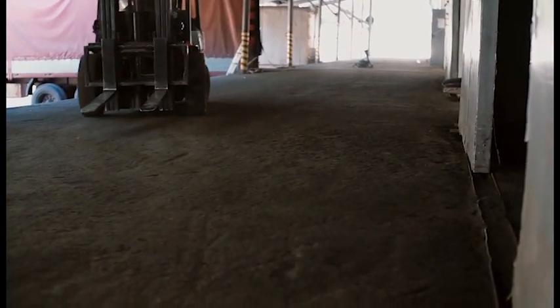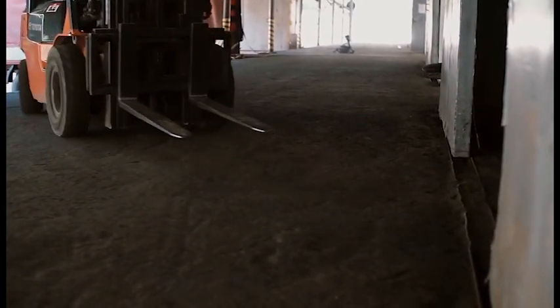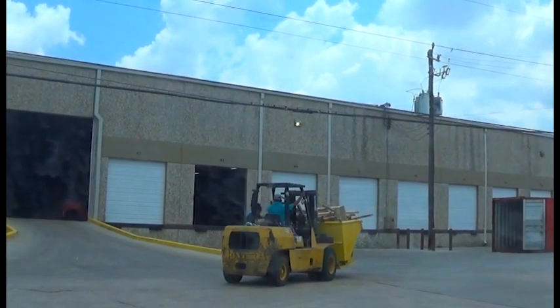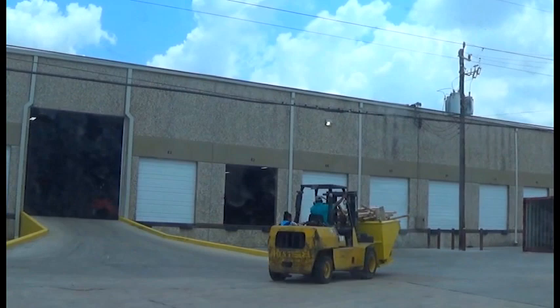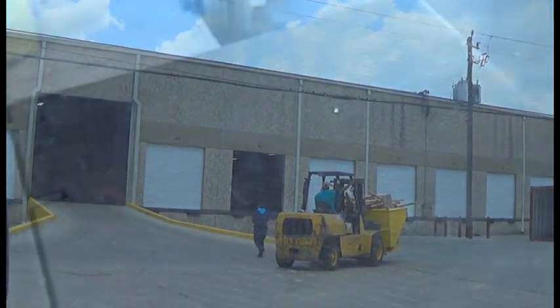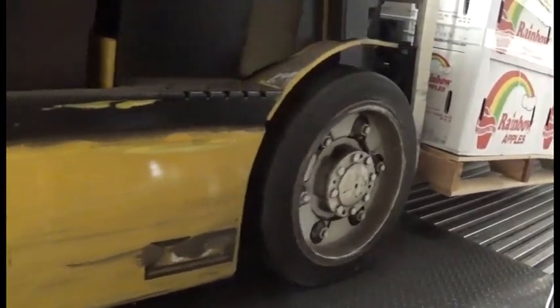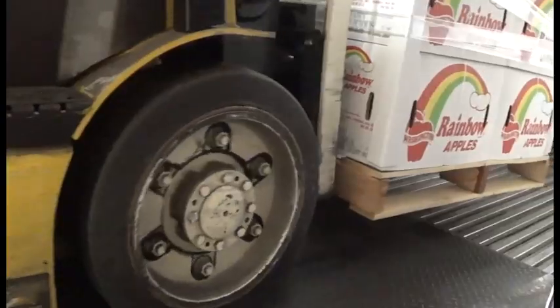Drive slowly into and out of warehouses or other buildings. Going from bright daylight into a darker warehouse could cause impaired visibility. Stunt driving and horseplay are never allowed. Dock boards or bridge plates must be properly secured and driven over slowly and carefully. Their rated capacity must never be exceeded.